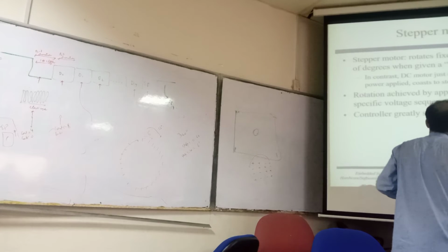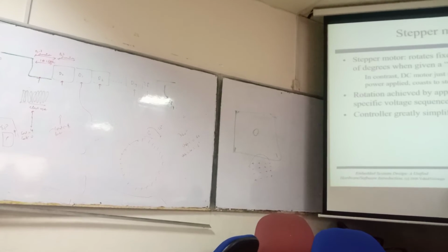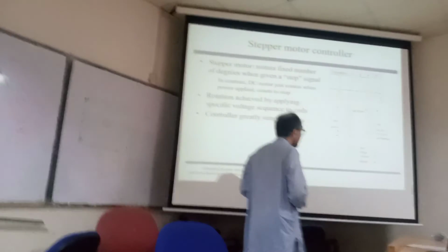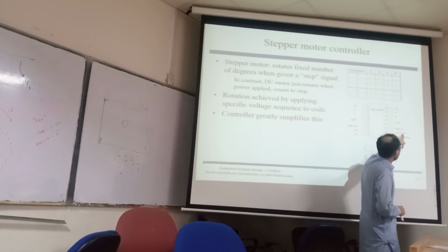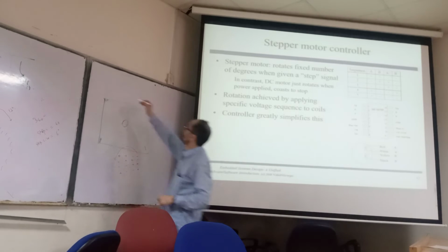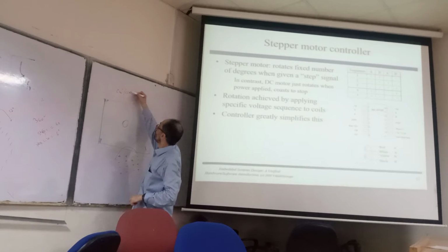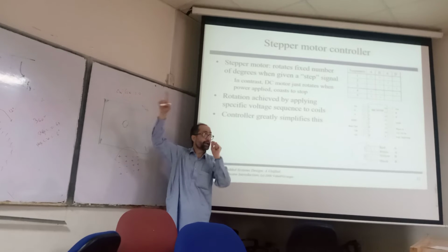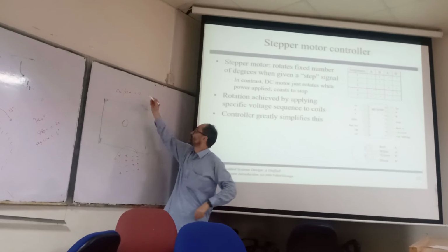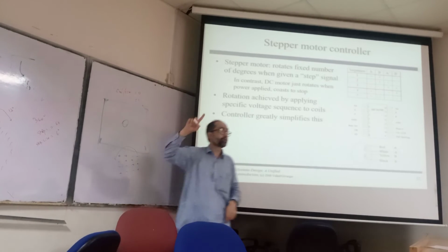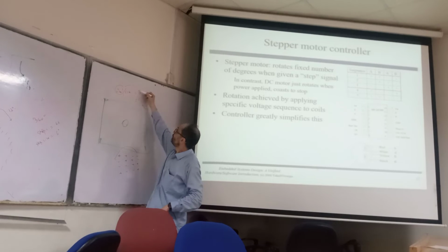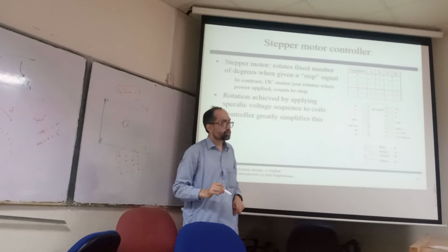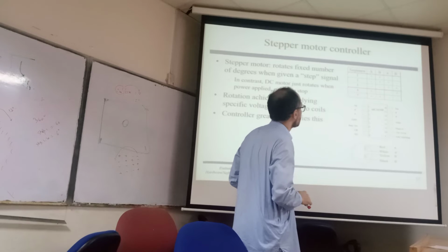Now if you look at this IC, MC3479P, there are CW bar and CCW. What does CW bar mean? Clockwise or counterclockwise. CCW. So when it's 0, it will move in a clockwise direction. When it's 1, it will move counterclockwise. Why? Because there is a bar. Bar is active low. So when it's 0, it will move in a clockwise direction. If CCW is 1, it's anti-clockwise.